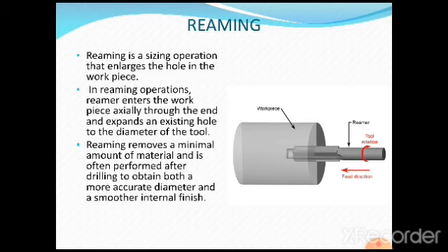We cannot carry out the reaming operation directly like drilling. First I have to drill to a certain length in a workpiece, then I have to carry out the operation of reaming, but the operation is just similar to what we have discussed for the drilling.